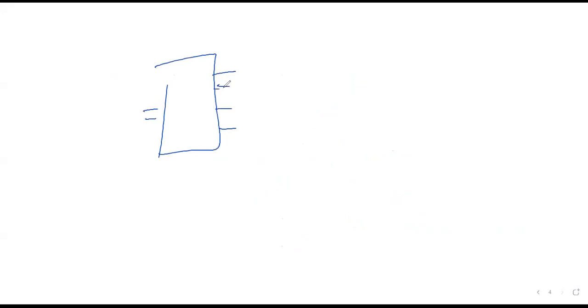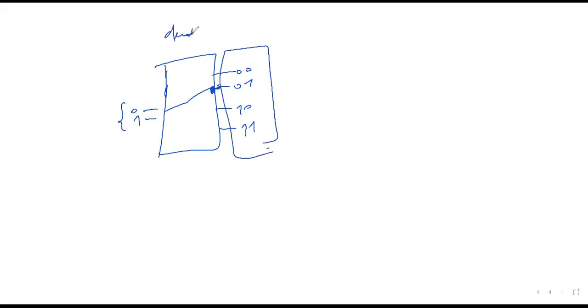This is a decoder, right? If I select 0, 1, 0, 0, 0, 1, 1, 0, 1, 1. If I select input 0, 1, it means in my bank of memory, whatever it is, I go and select this one, 0, 1, here. This is my memory here. My memory has all this. But with the use of the decoder, in this case, if I input a 01, it means I can only access this memory.